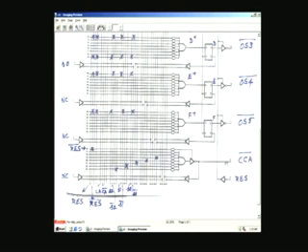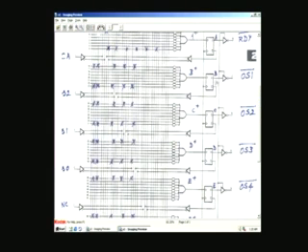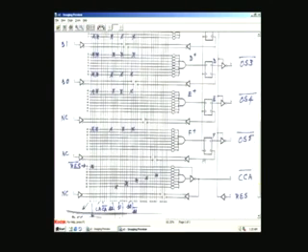And CCA is, as I said, the combinational output of B, C, D, E, F. So B, C, D, E, F are also fed back. B, C, D, E, F are the flip-flop outputs, YS1, YS2, YS3, YS4, YS5. They are also fed back as inputs. So we can get this CCA output from this. Again there is a negative logic here, there is an inverter, the output of the OR gate, so it is CCA bar. And reset is given here because it resets all the flip-flops here.